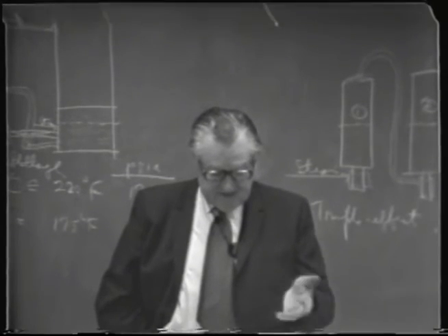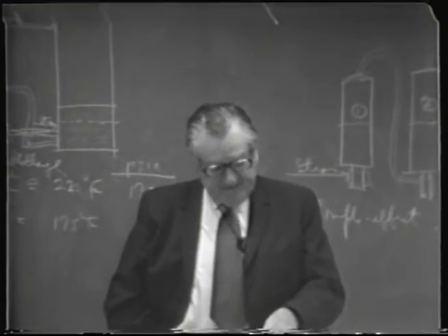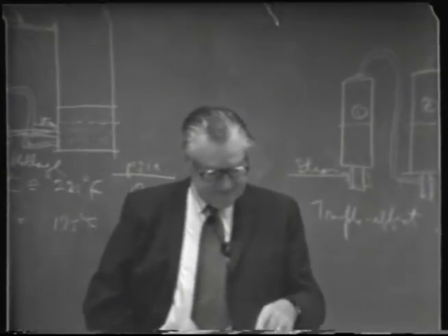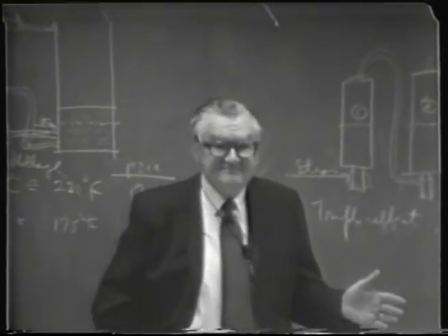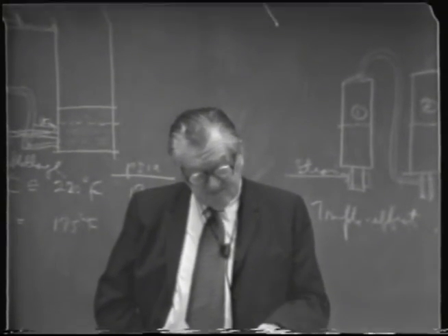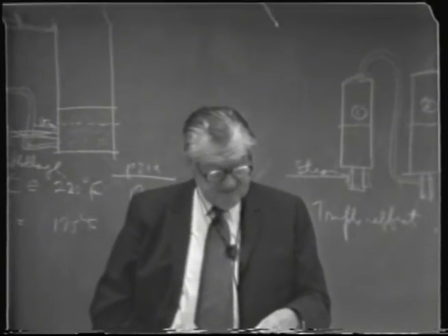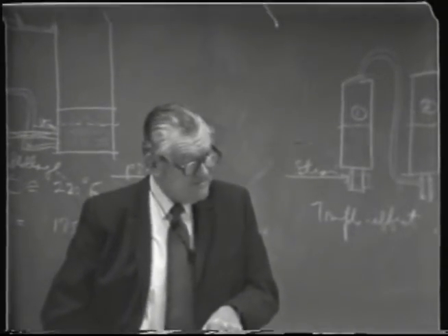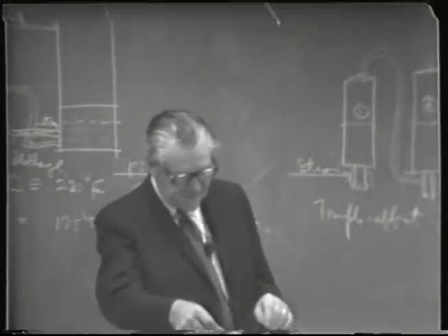But if you say we're making high proof and fed it at 192 proof, and the concentrated heads comes off maybe at 193 proof, the bottom's product would come out and be only a fraction of a proof less, or maybe 191.8 or something like that. If you're feeding in beverage brandy at 170 proof and taking off a heads cut at 193 proof, well, then there might be a little bit larger drop in proof going out the bottoms past the reboiler. But it wouldn't be very significant either.